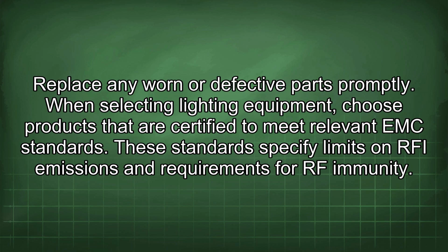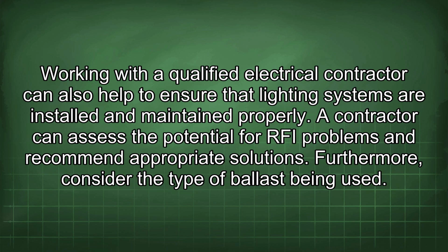When selecting lighting equipment, choose products that are certified to meet relevant EMC standards. These standards specify limits on RFI emissions and requirements for RF immunity. Working with a qualified electrical contractor can also help to ensure that lighting systems are installed and maintained properly. A contractor can assess the potential for RFI problems and recommend appropriate solutions. Furthermore, consider the type of ballast being used.